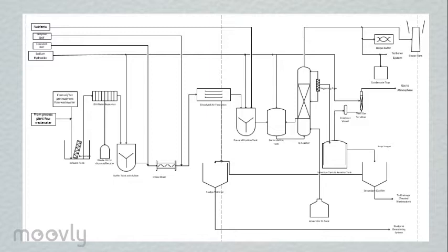After anaerobic treatment, the wastewater will flow to an activated sludge system for further removal of remaining biodegradable chemical oxygen demand, COD. The activated sludge system consists of an aeration tank and a secondary clarifier. In the IC reactor, the byproduct, namely the biogas, is produced.